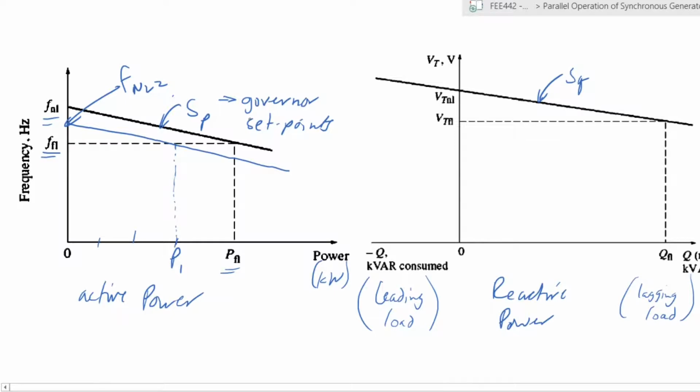All right. So what that means is, imagine that your governor is running without being connected to any load. It is isolated, disconnected from everything. It is just the prime mover rotating the alternator, and you're measuring the frequency coming out of the terminal points. At no load, at zero, you could set the governor to adjust the speed that it is outputting.